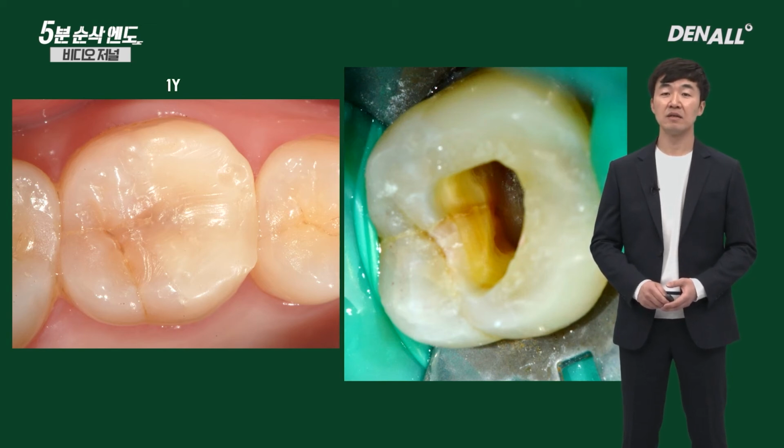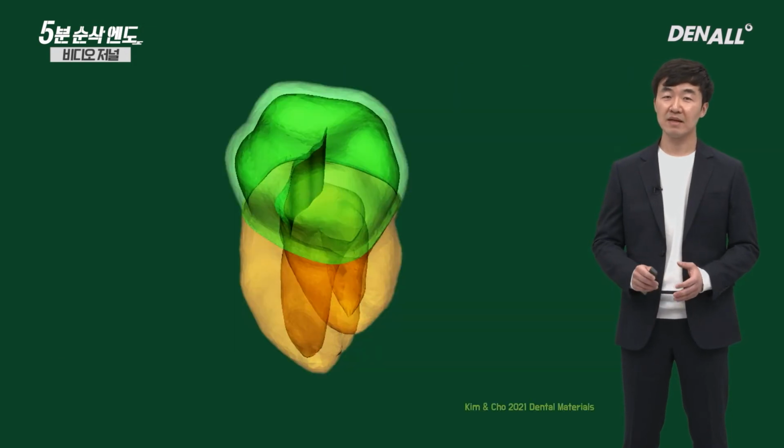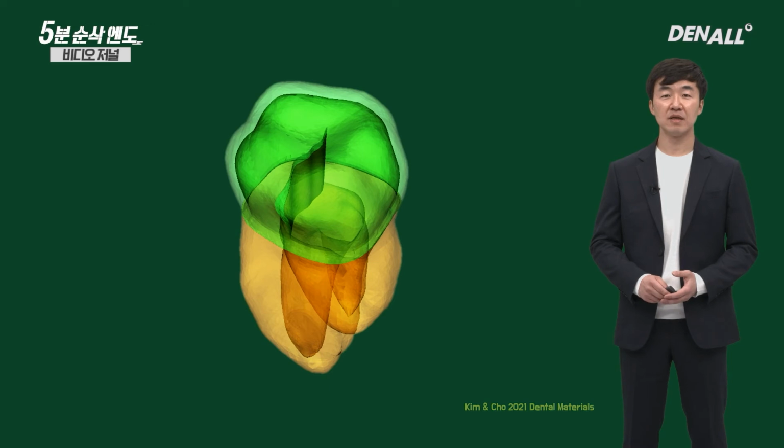I wanted to see how occlusal force is delivered to the internal structure of the tooth and how much stress is focused on the area where there was a crack. It is clinically impossible to apply different treatment modalities on a cracked tooth, so I used a finite element method, which is a type of computer method.